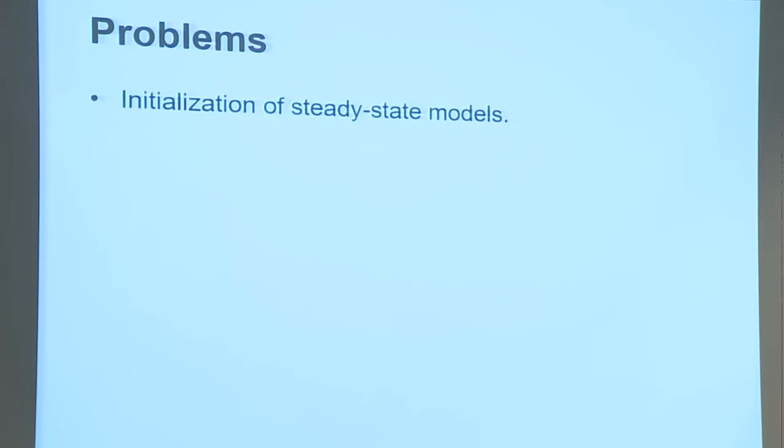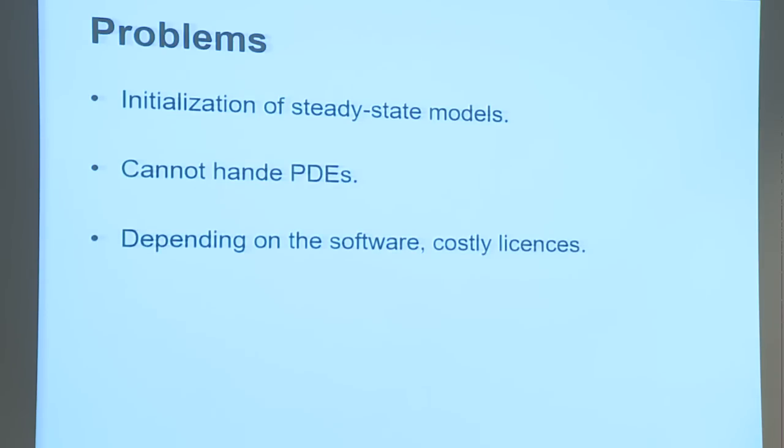That is one of the problems I faced, and it makes things difficult. But I think that is not a problem of Dymola, that's just a problem of steady-state models. But in Dymola, defining starting values is not the nicest, because you have your full model, and that is translated afterwards into a simplified model. And there you just don't know which variables it uses. Second problem: Dymola cannot handle PDEs. So if you have to model PDEs, Dymola or Modelica is not the language you want to use at the time being. It's constantly updated, but at the moment, it cannot handle PDEs. Yeah, but usually you semi-discretize PDEs anyway. You can, exactly.